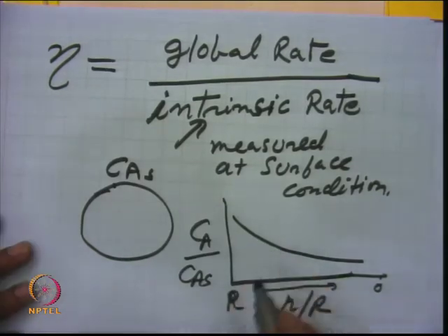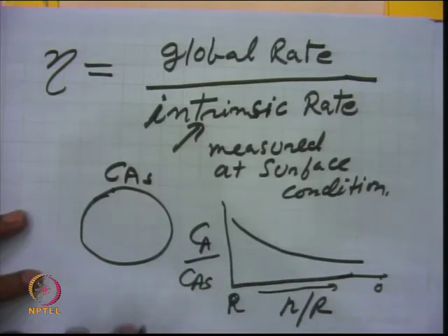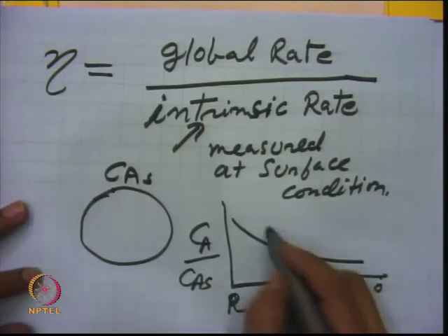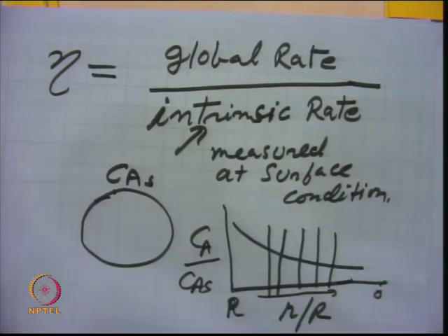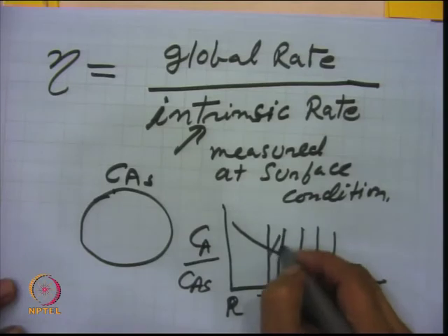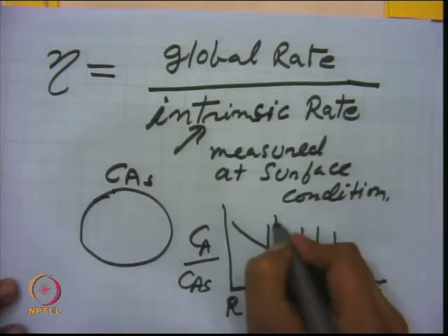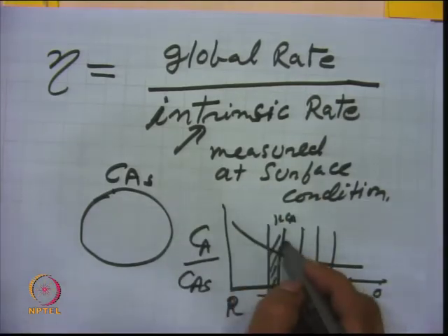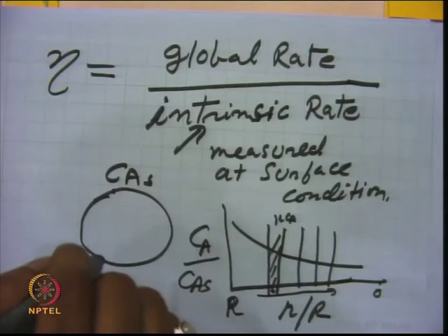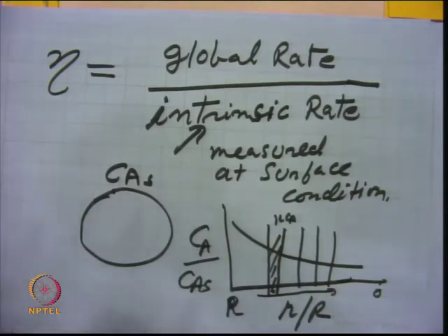So, if you need to calculate the rate, which concentration will you take? You have to divide it into differential zones, and for that differential section calculate the rate and then integrate it for the whole pellet. So, it means something which is to be done based on the rate at differential Ca value. Suppose you are writing Kca here and then integrate it. So, Kca for the differential cell, which you know now that you have already done that expression.